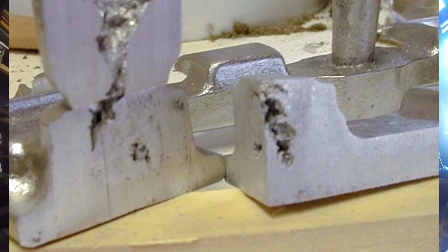So that riser should have been at least almost all the way to the edge of the casting, if not past the edge of the top of the casting right there, to feed it properly. Usually the only time that anybody makes this kind of mistake is that they're worried about the amount of time it's going to take to remove the riser and then machine the casting.